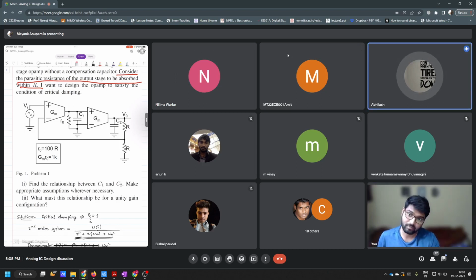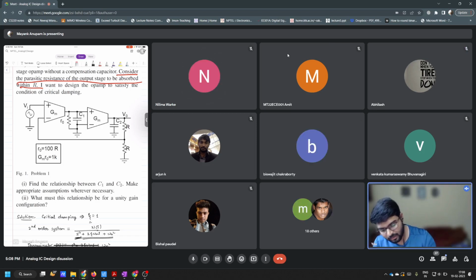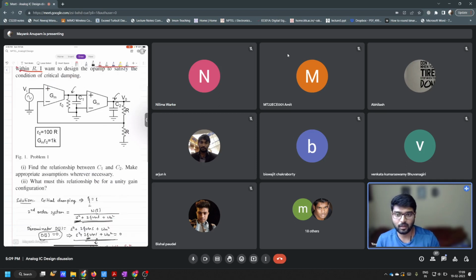Sir, we have two capacitors C1 and C2, storage elements. Correct. Because there are two capacitors here, there are two poles in the system. These two capacitors are separate capacitors, isn't it? And on both these capacitors, initial conditions can be fixed independently. So these two capacitors are independent of each other, and they are setting independent poles, right? That is why you have two poles here.